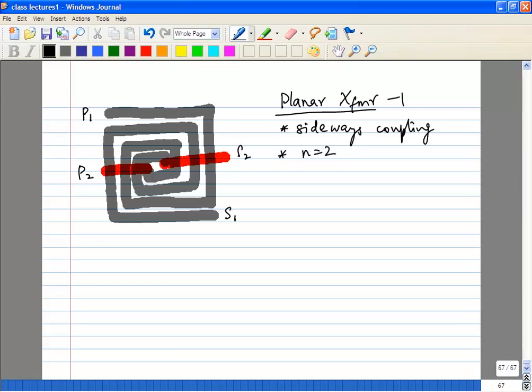And the other thing, of course, you note is that P1 and P2 are not symmetric. Similarly, S1 and S2 are not symmetric because now you have this on a lower layer, or you have larger capacitance at this node, right? They are obviously not symmetric. Even though the primary and the secondary are symmetric, the 2 ports of the primary are not symmetric, which may be okay in certain cases. Okay? So now the other kind of transformer we'll look at is this.